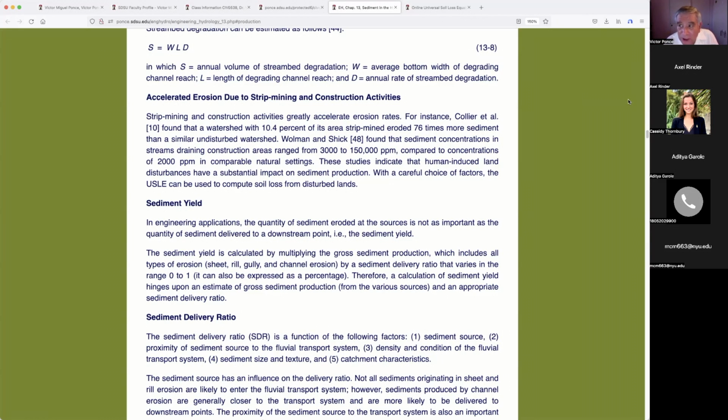They call it sediment retention basins. The rationale is the flood is going to come and it's going to carry a lot of sediment, and we know how much because we can calculate that. That has been done. I'll talk about that later. How much sediment can you expect during a flood from the water that is moving swiftly at this time? When it used to move like a foot or 2 feet per second, now it's moving at 5 feet per second, right? So it's carrying a lot of sediment. So they were successful in the year 1992, by the way, in building the 2 dams. And I have pictures of that. I'll show it to you later on.